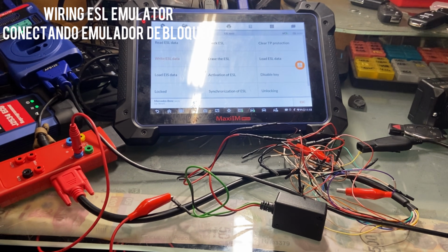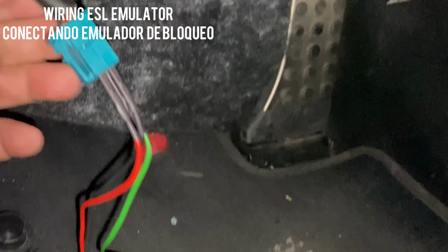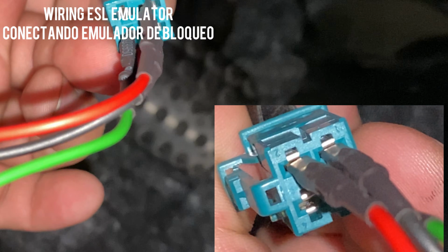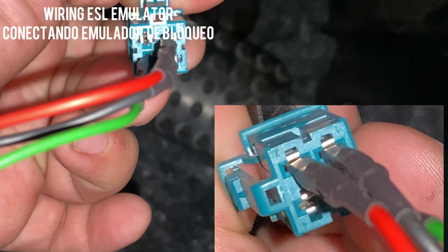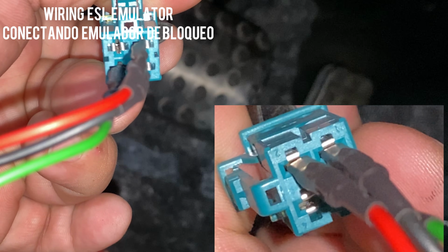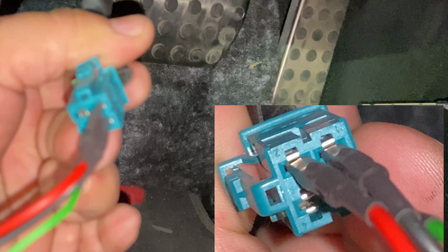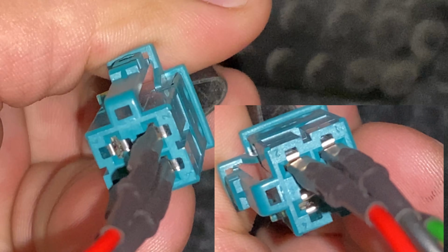All right, you guys, so here is the difficult part. So the ground is going to go to where pin 1 needs to be at. The power is going to go where pin 2 needs to be at. And then the green wire is going to go to where pin 3 needs to be at, okay? You guys can see that there's a number actually written where each pin goes connected to.